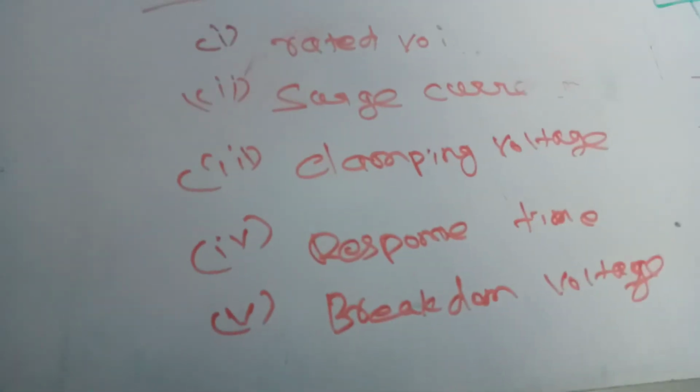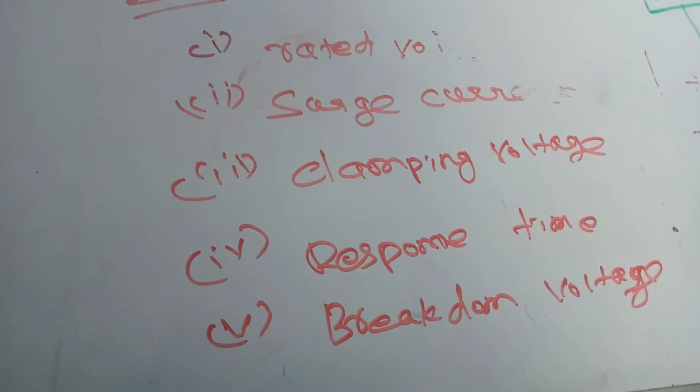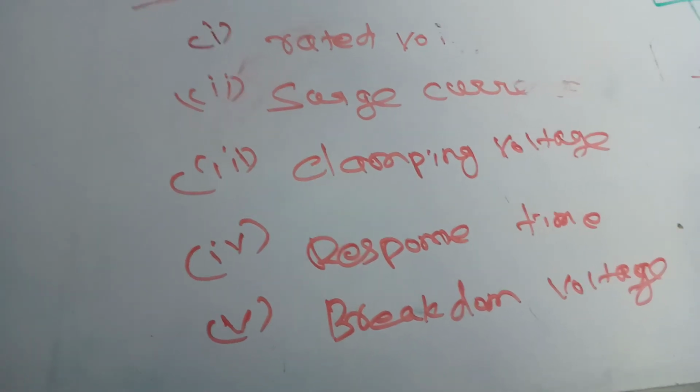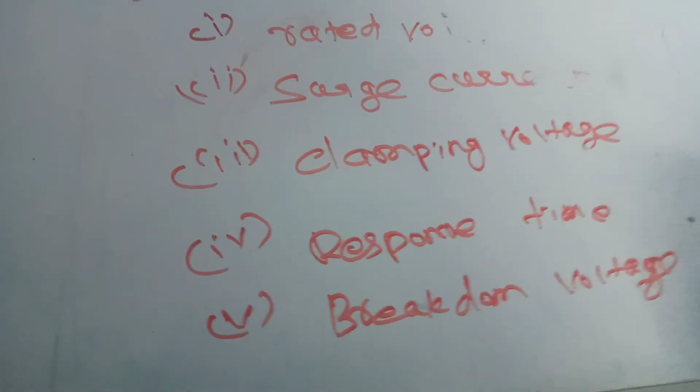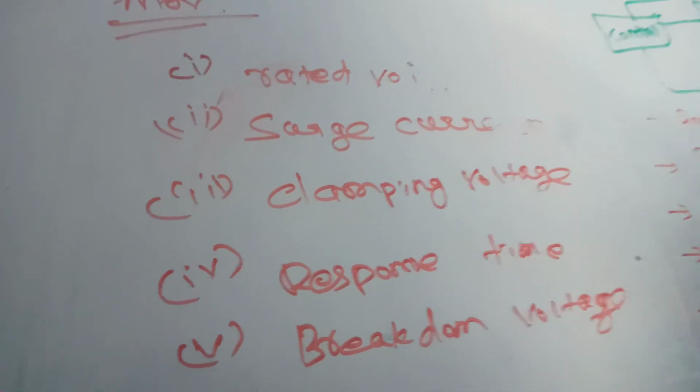So that is how you have to choose the MOV parameters. We need to choose how much you need. Some people say different sizes, MOV of 8 mm, 14 mm, or 20 mm. So this parameter is important for choosing the MOV. Next, coming to the bridge rectifier.